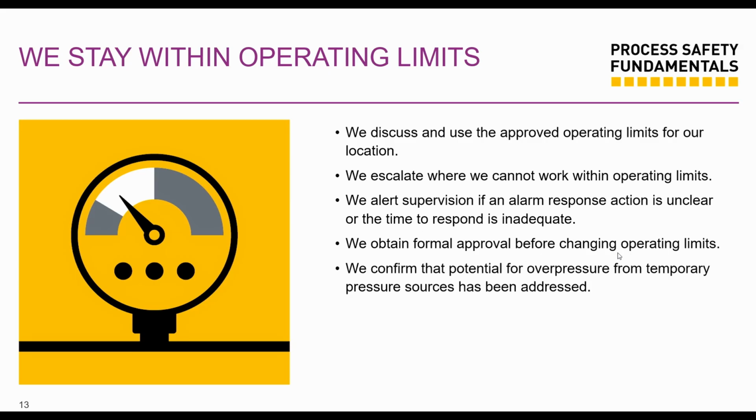Also, obtain formal approval before changing operating limits. This should be like a full MOC. You're changing your operating limits, you're increasing pressure, you're increasing your temperature, you're increasing flow. We should actually carry out some serious engineering investigations before changing our operating limits, and also confirm that potential for overpressure from temporary pressure sources has been addressed, because you could have overpressure, and you want to make sure that your system can handle that.